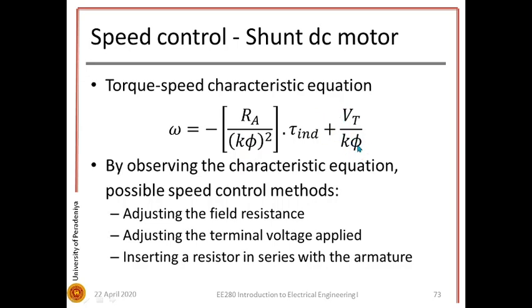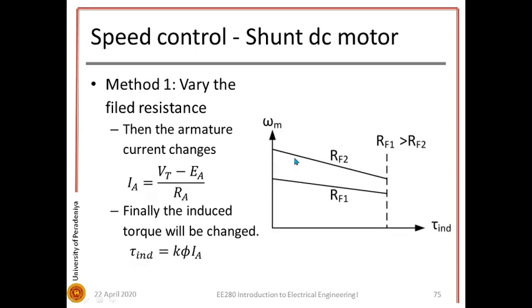So when you have low flux, your intersection point would be higher, and when you have higher field current, it is going to be intersecting at a lower value. And similarly for the gradient, if you have a higher field current, then the gradient would be less, and if you have lower field current, the gradient would be high. So that you can relate here.